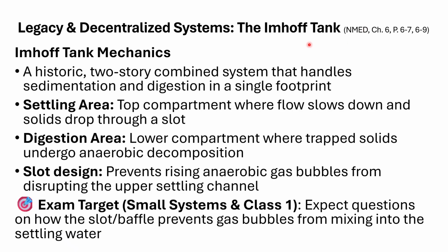There's this thing called an Imhoff tank. Remember last time we talked about measuring suspended or TSS concentrations using an Imhoff cone? We're going to use that process of settling, or we used to use that process of settling in rural areas with what's called an Imhoff tank. I call it historic because you'll still see some. We're not building anymore. Nobody says, "Oh my God, I got to have me an Imhoff tank for my new wastewater treatment scheme in a rural area." No, but there's still some out there, so we should know about it.